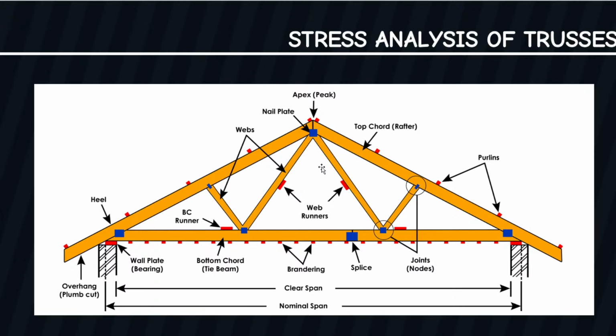So, in building design, where an open and unobstructed space with a width of more than 40 or 50 feet is to be provided, the roof is commonly supported by roof trusses spaced from about 15 to 25 feet apart. These trusses may rest on columns or on masonry walls along the sides of the building. A roof truss attached to its supporting columns is commonly called a bent. The analysis of which will be treated in the next lectures. The discussion in this lecture will be limited to roof trusses supported on masonry walls.